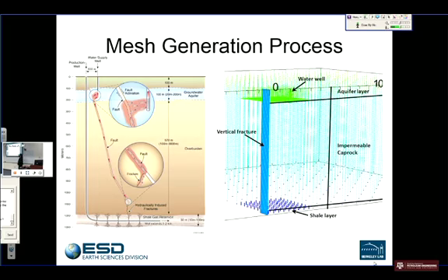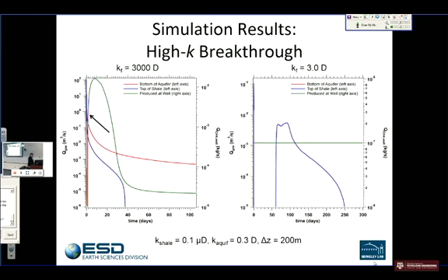And this is the three-dimensional grid that we have developed for this. It's extremely complicated. We had to use Voronoi grids for this. It's several 100,000 elements. Non-isothermal, because the temperature between this point and the shallow aquifer can be very significant, so we cannot assume it's isothermal. And this is an example, nothing more than an example. Here, what we have is a high permeability fracture connecting the reservoir to the shallow aquifer. So this is what happens at the top of the shale.